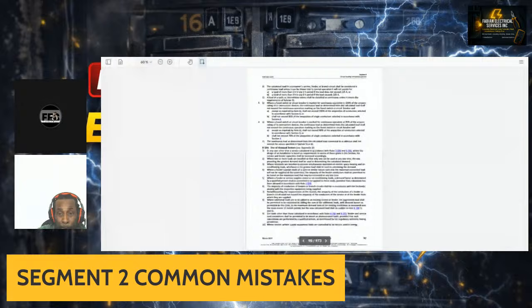So right here, I have two different types of breakers. One of them is a 20 amp two pole breaker. This is a 15 amp single pole breaker. So oversizing, or undersizing we can say, is if you take a 14 gauge wire and you place it on this breaker here. This is a 20 amp breaker.